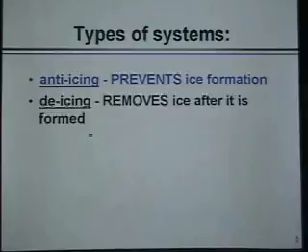However, some of these systems, although they're designed as a de-icing system, may work as an anti-icing system, and some of the anti-icing systems may work as a de-icing system, and it's important as a pilot to know if you can use an anti-icing system as a de-icer in case you get into that situation. So as we go through these systems, I'm going to tell you, well, this one is designed as an anti-icing system, but it will or will not work well as a de-icing system, and vice versa.